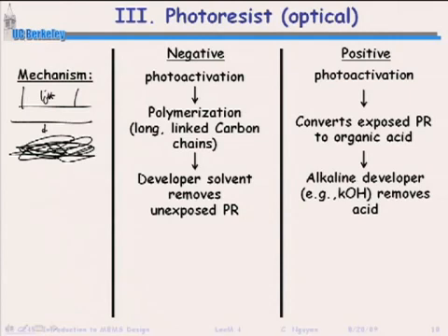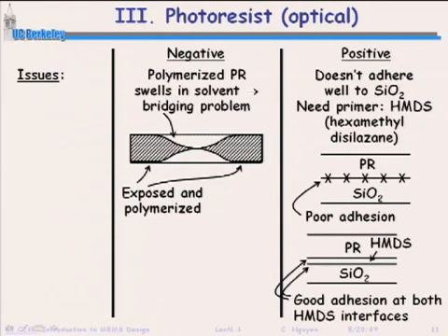In the end, which is better? Positive resist, a lot of people think is better. And part of that's because in a negative resist, when you have to polymerize, it's hard to do that as a step function. Right? So what you'll get is something like this, where here's where everything is strongly polymerized. It's all a polymer on that side. But you still get tails that go into this. So if you were trying to create a feature like this, you would end up really creating a feature like this, which means that you're not getting as sharp a step in that photoresist as you'd like to have.